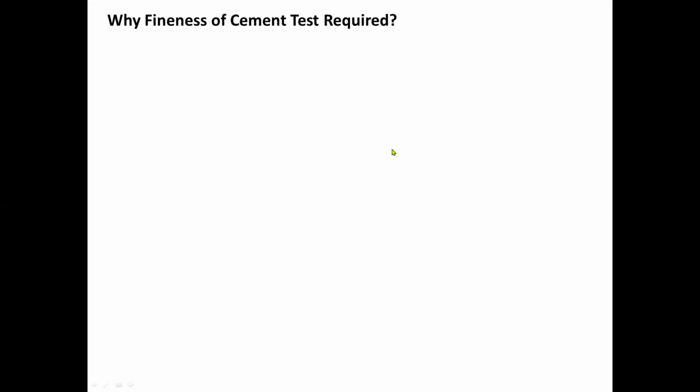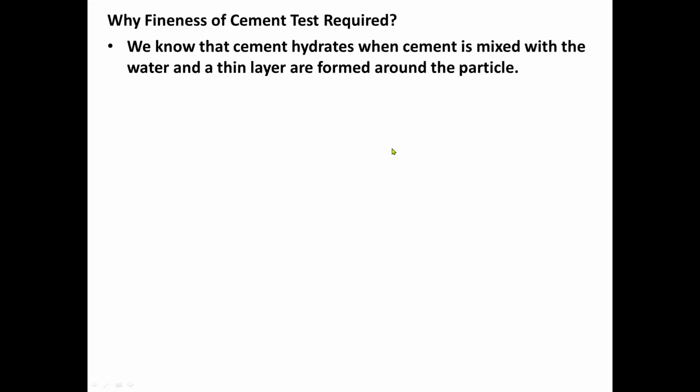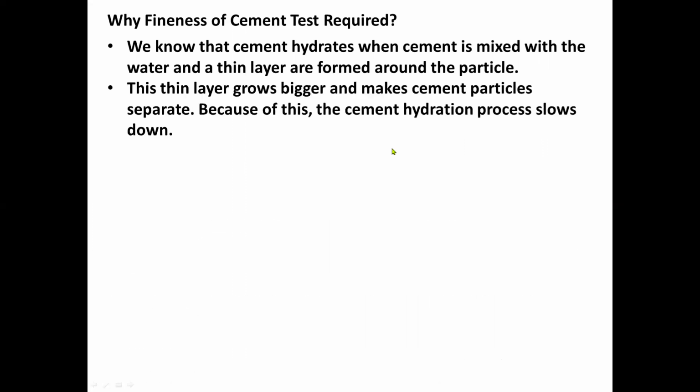Why is the fineness of cement test required? We know that cement hydrates when it is mixed with water, and a thin layer is formed around the particle. This thin layer grows bigger and makes cement particles separate. Because of this, the cement hydration process slows down.